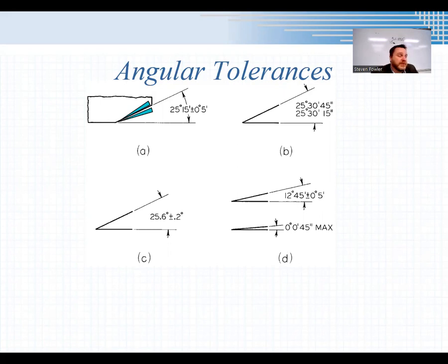We can specify angles with smart dimensions in SolidWorks the same way I do dimensions, right? I can click between two lines and specify the angle between them. If I've drawn a rectangle and it's already specified as 90 degrees, SolidWorks is not going to let me specify the angle there. But if I've just drawn two lines arbitrarily, I can specify the angle between them. Just smart dimension one, click on the other one, and it'll let me set the angle between them. You can specify tolerances with how much above or below a specific basic value that angle should be.